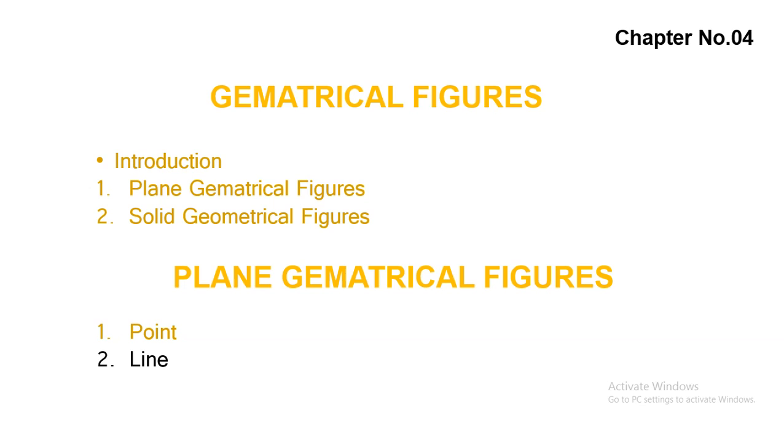There are many types of lines: main object line, construction line, dotted line, center line, break line, section line, cutting plane line, dimension or extension line, etc. Some of them are applied lightly and some are applied darkly. The light or dark line is called the weight of the line.